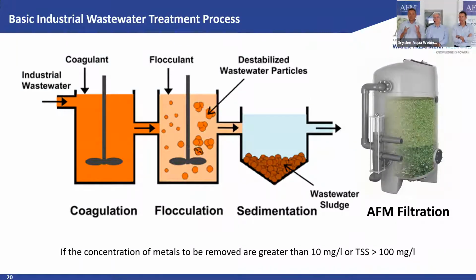Gravity is the cheapest way to filter. That's the cheapest one. And AFM is fine filtration. This is the polishing step. It's not the heavy filtration. Otherwise, you have to backwash the filter, I don't know, every half an hour. And that's probably not what you want to do.